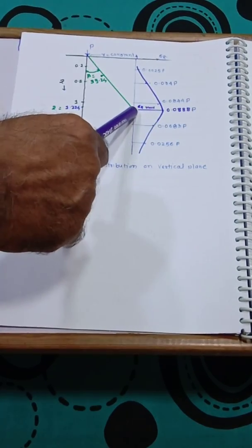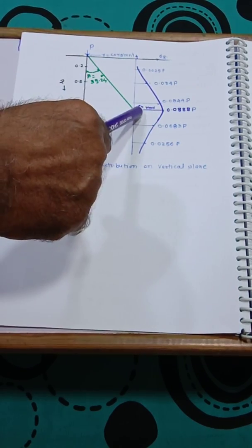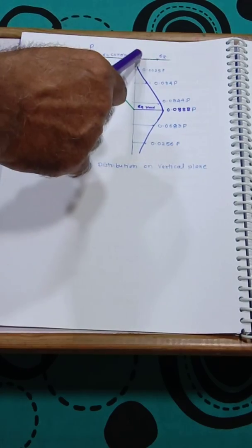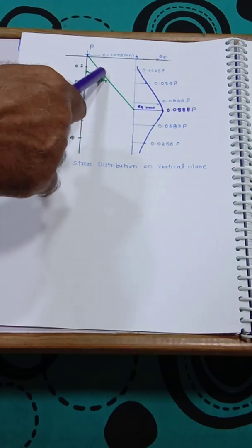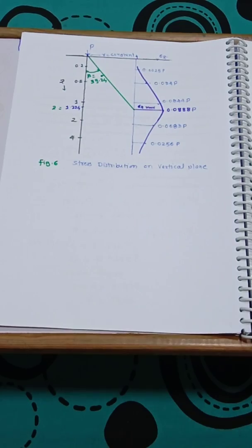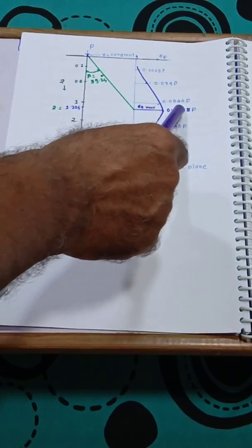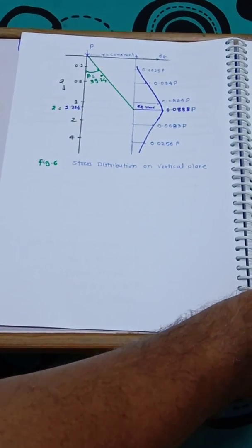Now what is this point, or what is the angle at which this is maximum? What is the angle between the constant R distance and Z? So Z is equal to 1.224 and the ratio of constant R we have taken. If I take tan of that and find this angle beta, I get 39.24. At this angle, the stress is maximum. So this is the stress distribution on a vertical plane. Here we completed the stress distribution on the horizontal plane and the stress distribution on the vertical plane.